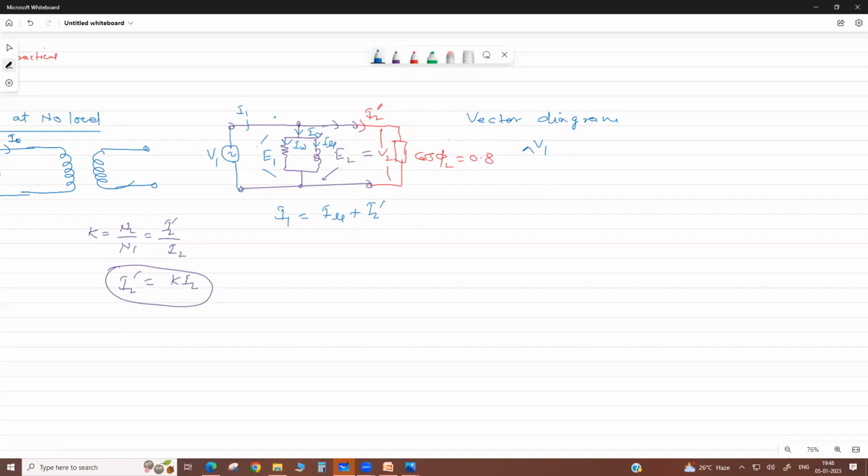Why is the rating of a transformer in kVA? See, the load on a motor is mechanical load, so the power factor is already decided, meaning it does not depend on load. But in the case of an alternator and transformer, we connect an electrical load.